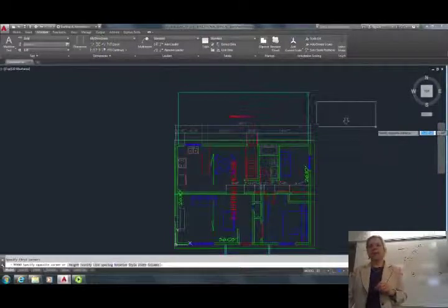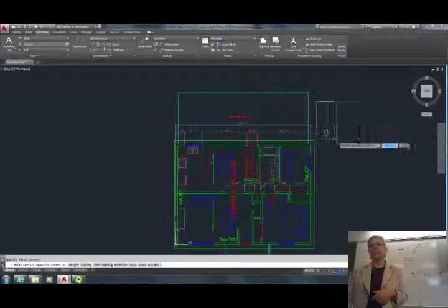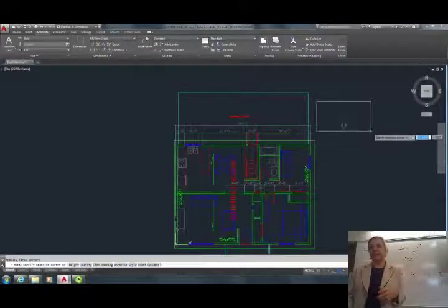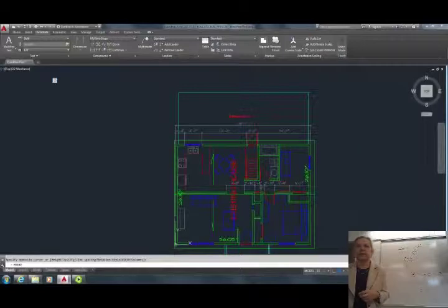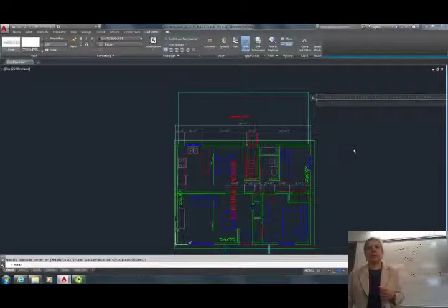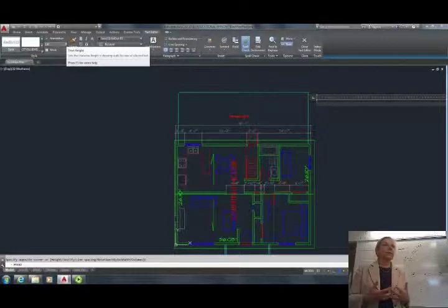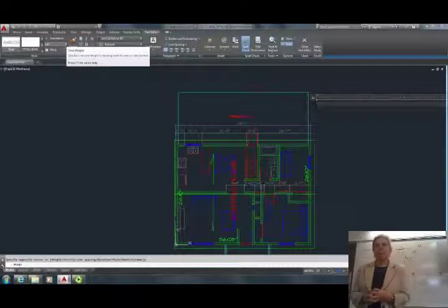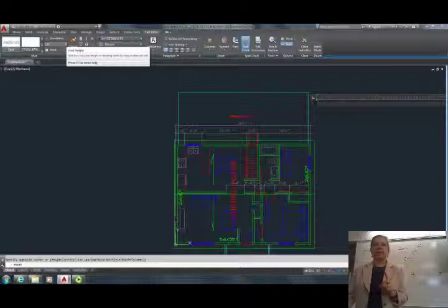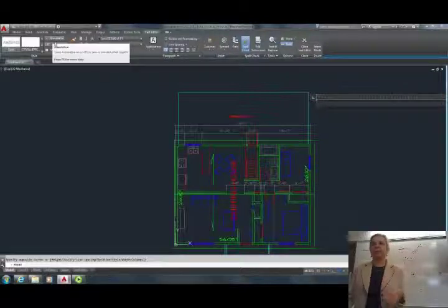and I don't want it bigger. I don't want it too small, but I don't want it bigger than this. So I'm going to click like that, and the first thing AutoCAD is going to give me is this information box, and the first thing that you have to look at is text size. My last note was done with 1/8 of an inch, and I am not choosing annotative because I want you to do high math.